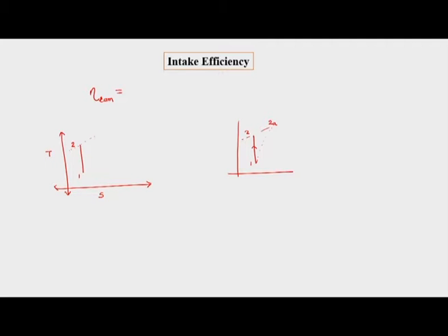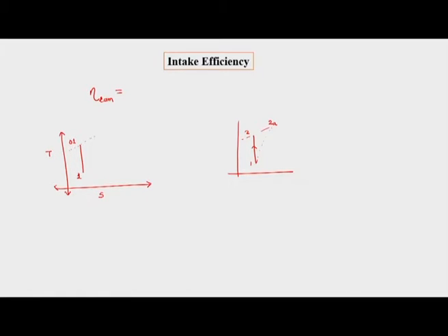but we would like to have the pressure rise in the intake such that instead of only a static pressure rise, we would expect it to reach the total pressure, which is 0 1. We have defined total or stagnation conditions as the conditions where we would have 0 velocity. We would have isentropically stopped the fluid and reached 0 velocity. So, 1 to 0 1. This is our expectation from the intake. So, we want the flow to go from 1 to 0 1 at the exit of the intake, that is our expectation.